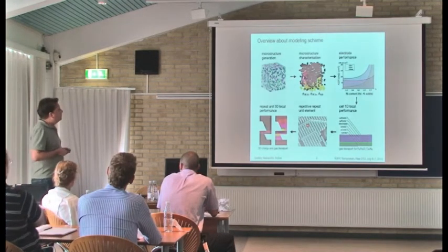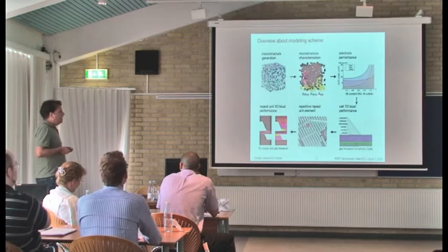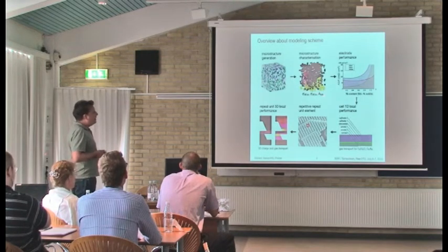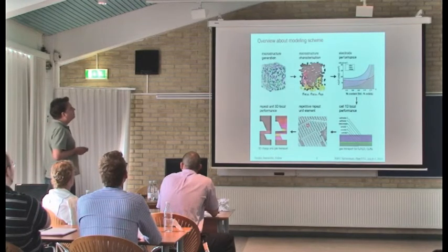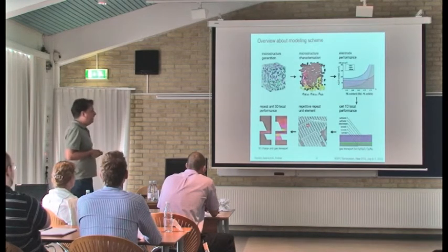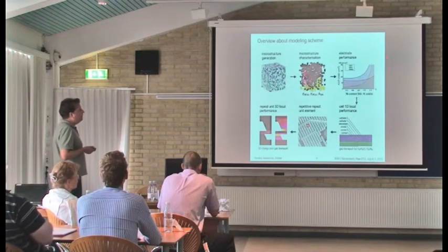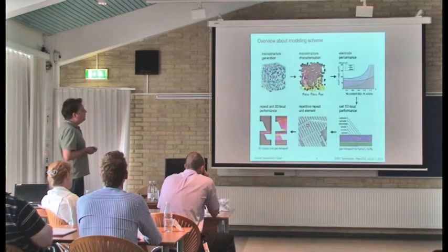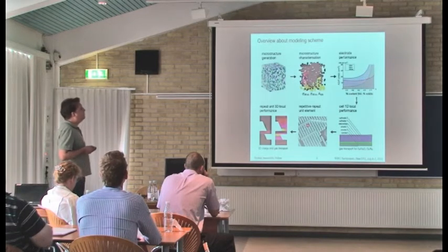In the results I'm going to show today, we extract the effective electronic and ionic conductivities, as well as, I should say, this is not the triple phase boundary length, the way it has been defined today, but the interface area between the two phases, which is in agreement with what has been done in the Costamagna paper. Then from that information, we move up to a continuum model, still finite element, but now you lose the microstructure information, it's all in your effective parameters, and you characterize your electrode. Here the total resistance is the blue curve, the polarization resistance is the red curve, and the brown curve represents the ohmic resistance as a function of the nickel content of your electrode.